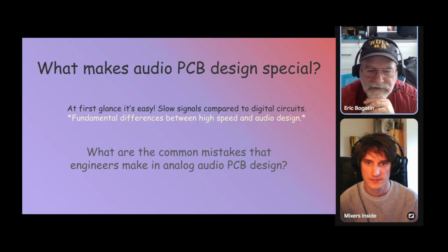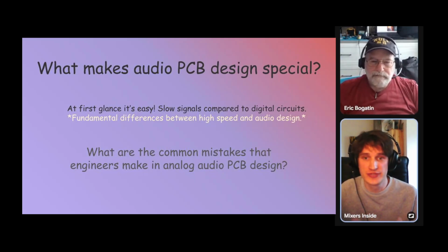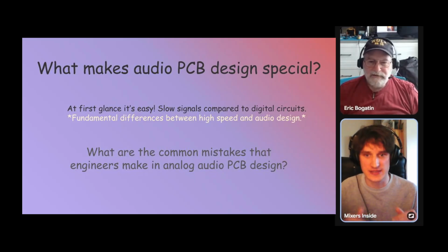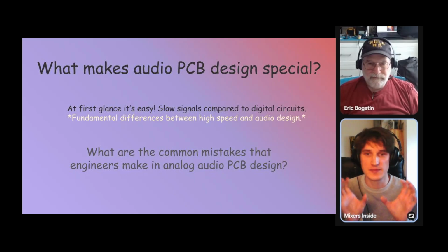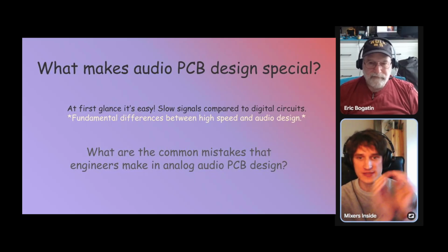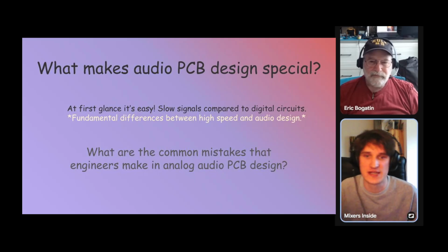Okay, so as I understand, our PCB design is critical to deal with noise and to keep the noise level low. Right. So what we can do about it is make zones on the PCB, like the digital zone and analog zone far away. Try to keep them from interfering with each other, right?